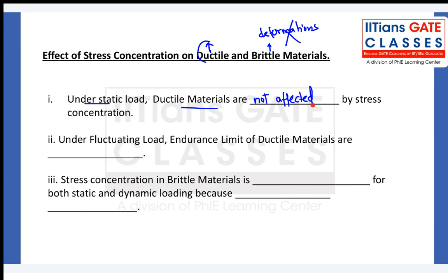Because of their capability of plastic deformation. The ductile materials have the capability of plastic deformation, and because of this plastic deformation, the discontinuities, the stress concentration, gets dispersed, it gets distributed.